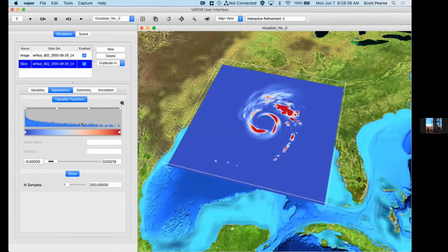So that's the distribution, but how is color and opacity being applied to these values? So we see this distribution, logarithmic on the y-axis, and color is being applied to these values based on this color bar that we see down here. So values that are 0 are deep blue, and we go through this color interpolation to white at the middle and then red at the end. That's how color is being applied. This is called a divergent color map because there are 2 colors that diverge from a midpoint. And divergent color maps are best suited for modal or bimodal distributions, but this is more of a linear distribution.